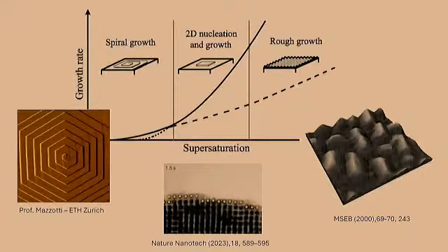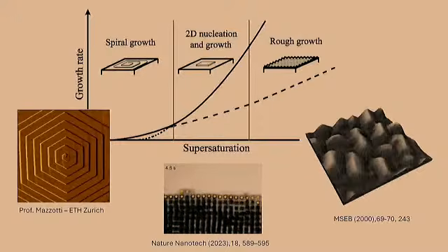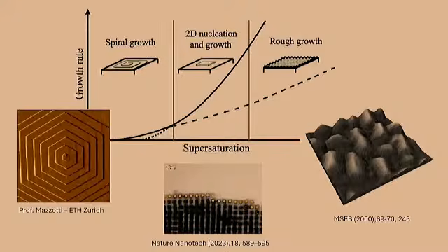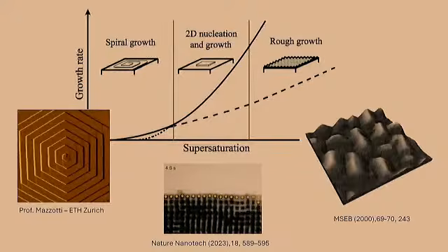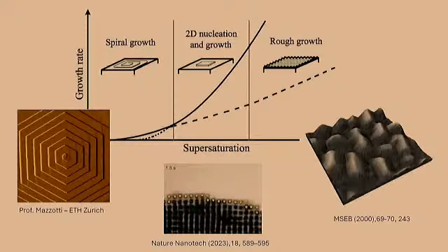Okay, it turns out that crystal growth under different supersaturations or driving forces happens in very different ways. In particular, when you have very low supersaturation, it grows by what's called a spiral growth mechanism. By the way, this is one of the first demonstrations that there are things called dislocations in materials, that crystals are actually growing under very low supersaturations where you don't expect them to grow. And people realized that it's because there are these screw dislocations that are present and so on, right?